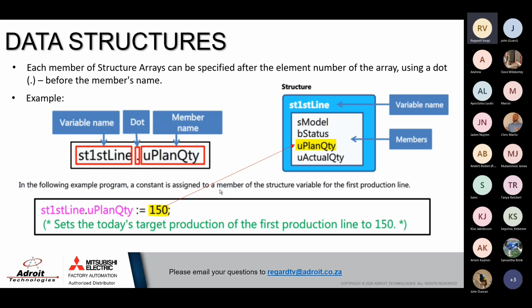So I just want to add another point regarding that. You don't have to adapt a structured text PLC program just because you have to do data handling and data structures. You can just combine a certain aspect of your PLC program in data structures and in structured text. The parts where you need to do arrays or string manipulation or data structures, you can write in a separate PLC program within your PLC. You can also combine them.